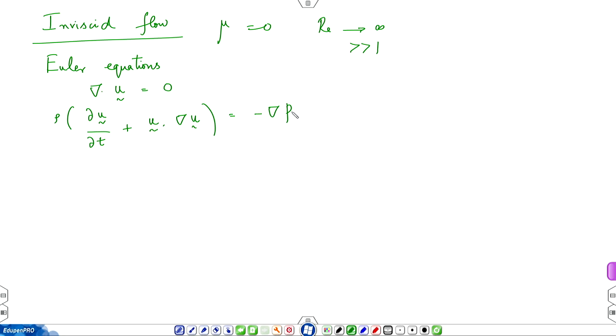We discussed this formulation in the previous class. The Euler equations per se are complicated because of the non-linearity. This is a non-linear acceleration term, but it affords great simplification if you introduce an intermediate variable called vorticity, omega, which is del cross u dot k. This dot k is required if you are going to carry out 2D calculations; otherwise you just do not have dot k, and it is still vorticity. Then it is a vorticity vector, but right now we are talking about scalar vorticity.